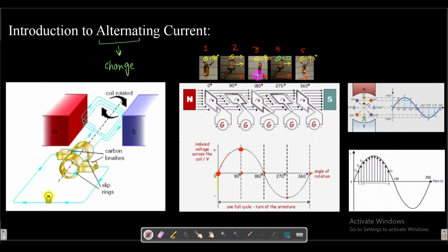And similarly again we have that same coil, but now its position is again vertical, and again here theta becomes 90, and when theta becomes 90, the magnetic flux becomes 0, and hence the EMF becomes 0, and it gives us this position. And here this again becomes horizontal, and theta is equal to 0, the magnetic flux will be maximum, and similarly the induced EMF will also be maximum, but in the opposite direction.